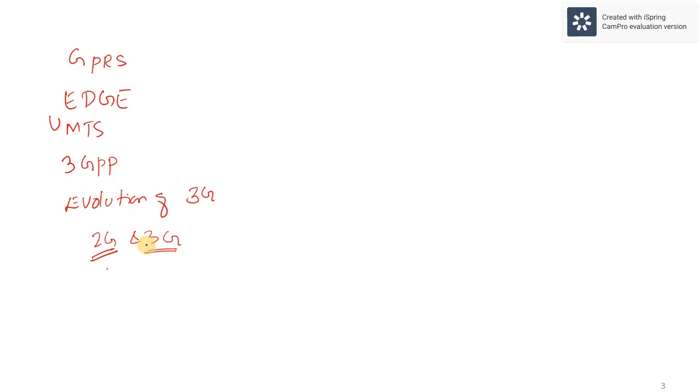So there is much simpler management of codes, and the base station can use the same orthogonal spreading codes. Precise synchronization is not necessary, as scrambling codes stay quasi-orthogonal. That is the advantage of this technique. And if you look at the frame structure, it will be different from that of the UTRAN network.